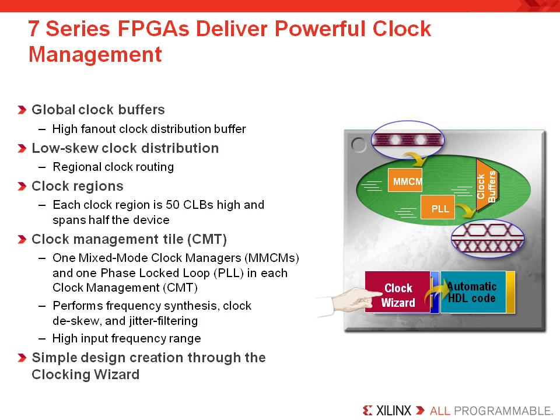The 7 Series has 3 different clock routing resources: global for your highest fan-out clocks, low skew for regional clocking, and I/O clock routing for SerDes resources. Now we'll talk about the specifics of these clock resources later on in the recordings and explain when you want to use each of these resources. The clock region structures are still important with the 7 Series family of devices. Note that the clock regions now contain 50 CLB rows, not 40 as they did with Virtex 6.